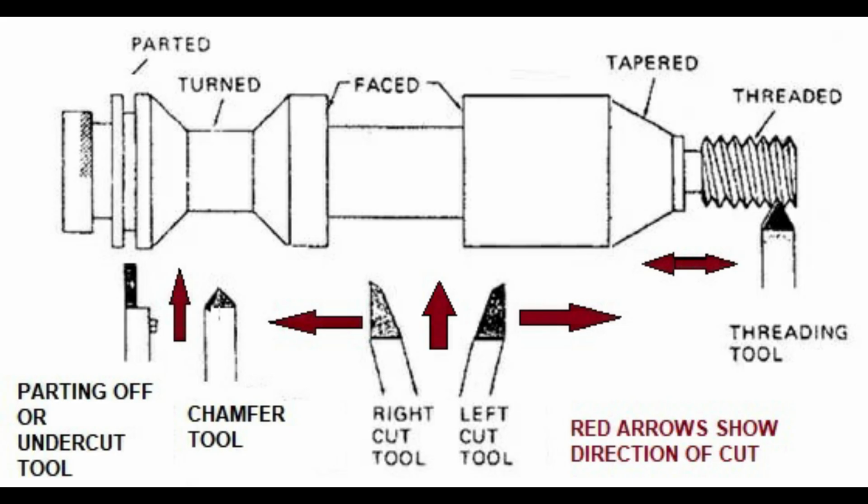Knife tools are generally used to turn the diameter along the axis of the workpiece. They can also be used for machining faces at 90 degrees to the workpiece axis, and for machining tapers, either by using a taper turning attachment or by setting the tool post to the desired degrees. Forming tools are more generally used by moving the tool against the axis of the workpiece. The speed for these tools is greatly reduced due to the broad cutting areas.